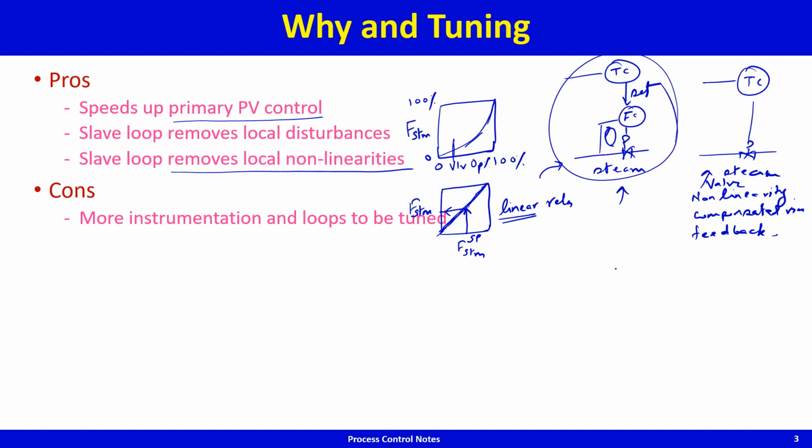So suppose you're controlling level, you got a tank, and you want to control level. Of course, I draw it for the sake of convenience. I'll usually say, okay, level is controlled by adjusting the outflow, but in practice almost always it will be in this way. There will be a flow controller, and then the level controller sets the flow controller set point.